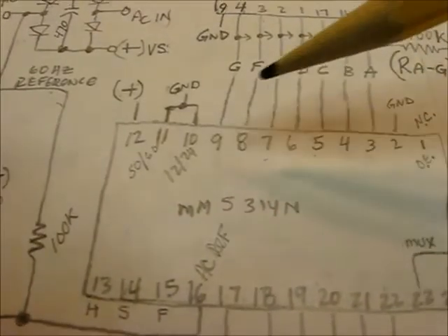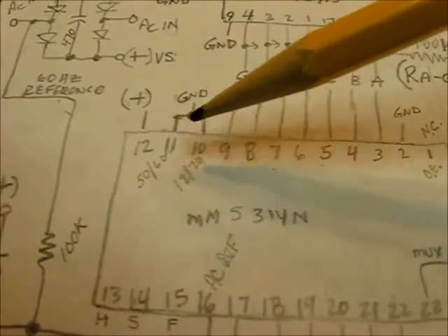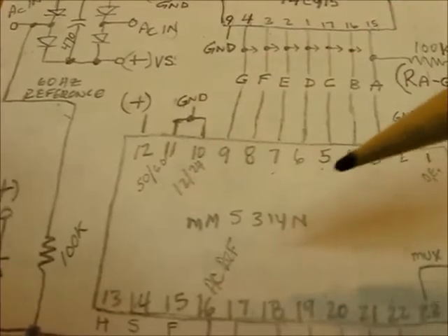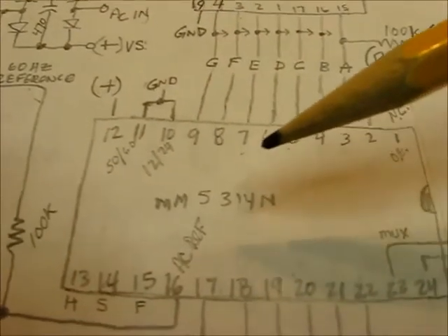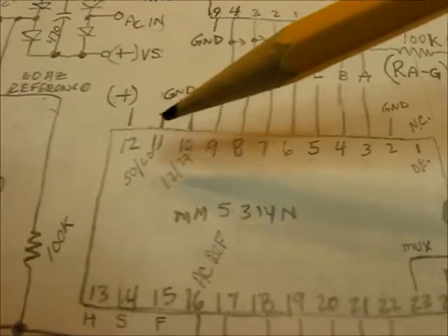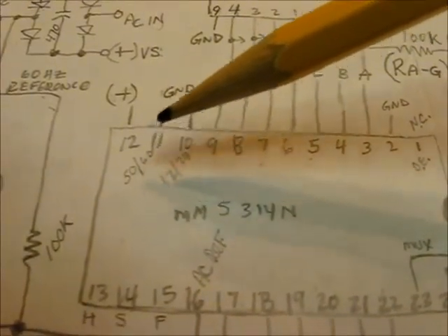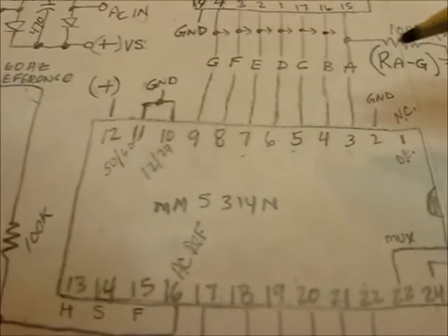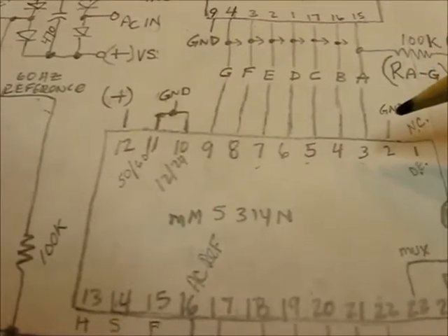Okay, same goes for the 50, 60 hertz selection. This chip will actually run on 50 hertz for those people that have that need. Here I'm going to ground that pin so it runs at 60 hertz. That's the same potential as, again, pin 2.